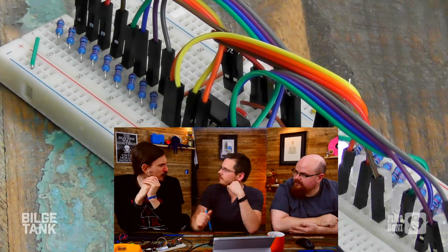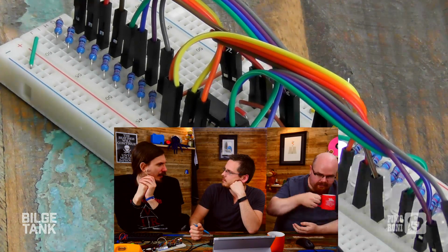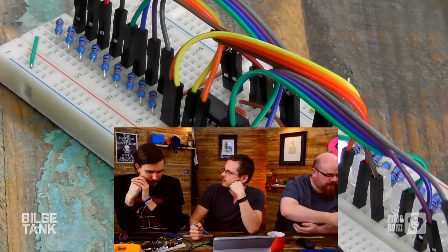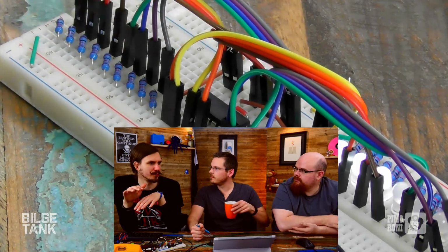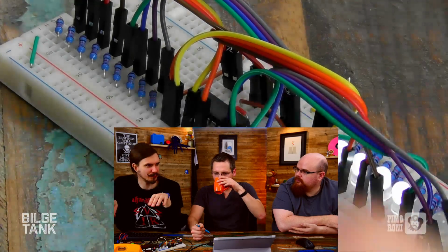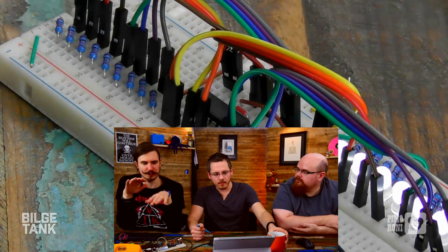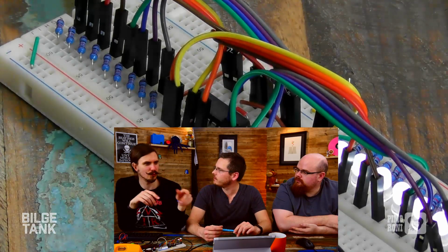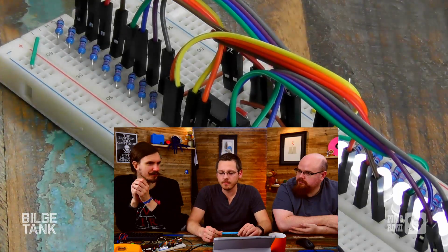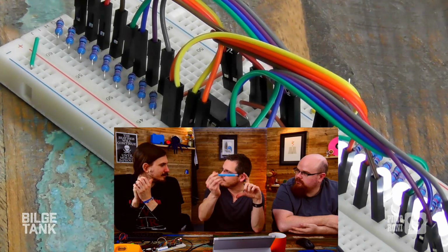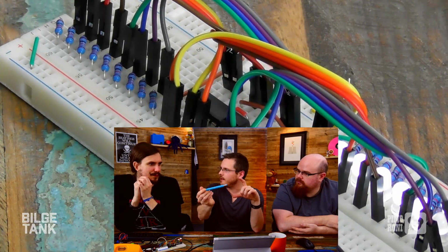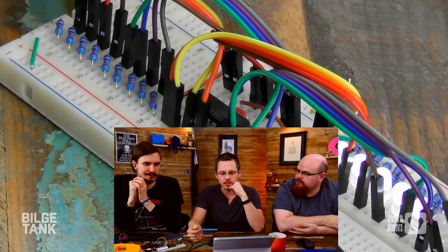So if you were doing something like measuring a light level and you wanted to do it entirely in discrete logic, for example, you could use a comparator against the reference voltage. Say if my light sensor voltage is higher than the reference voltage, then output 1, and turn on a light or something to that effect, or lower in this case. And you can tune your trigger by setting that reference voltage, so you can increase it to make the light level have to be higher, or decrease it to make it lower.